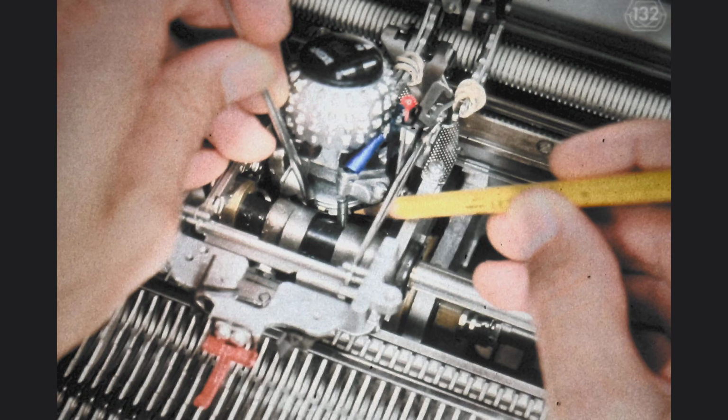Whenever we view the rotate spring from above, we rotate the spring cage clockwise to increase the spring tension and counterclockwise to decrease it. Rotating the spring cage clockwise to increase the tension is a simple matter, since the spring indicated by the yellow pencil acts like a ratchet, locking it in place every so often so the spring cage cannot turn counterclockwise and discharge the spring tension.